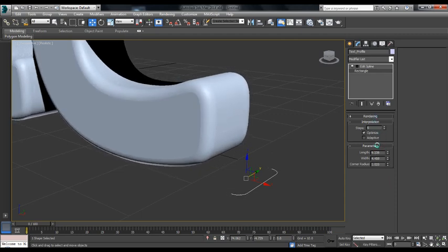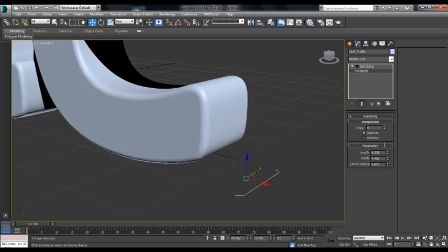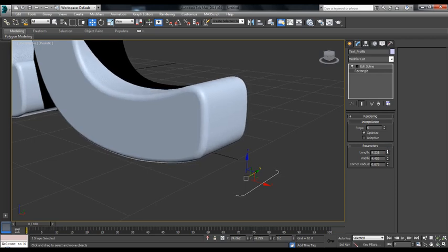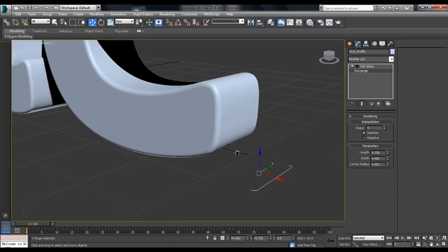This is a much more powerful method of creating 3D text than either the Extrude or the Bevel. I never use the Bevel modifier anymore. I always use Bevel Profile, which is what we're using here, or Extrude if I just want something rough to work with until I get round to putting Bevel Profile on.